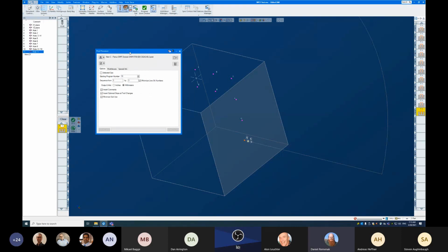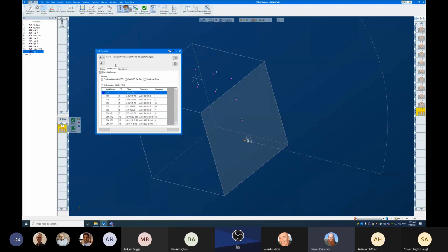Let's talk about the advantage here. Rescoping WFOs to be assigned to operations instead of CSs gives us a couple things. One is it gives a lot of flexibility and power to the user. So you can now assign work fixtures to operations regardless of what CS they're programmed in. Operations that are programmed in different CSs can share a WFO, or operations that are programmed in the same CS can be split into several WFOs. I'll talk about that in more detail and show you how to do that.